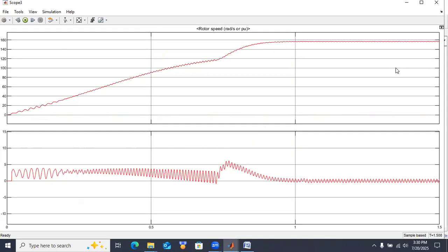We are simply combining two boost converters, and in between that we are creating one load, that is differential load. So across the differential load, we will get the differential output voltage, the difference between the right hand side and the left hand side converters. So from that voltage, we will get the AC output, and from the AC output, here we are connecting the motor in order to run that AC induction motor, single phase AC induction motor.